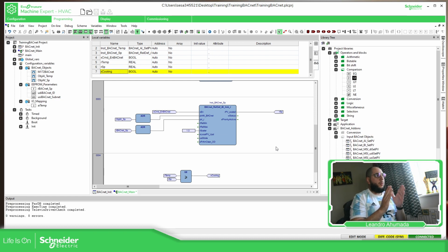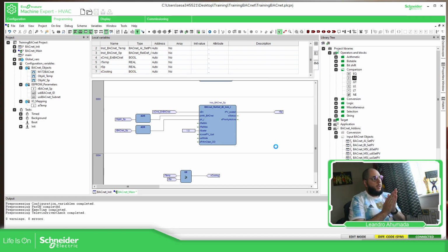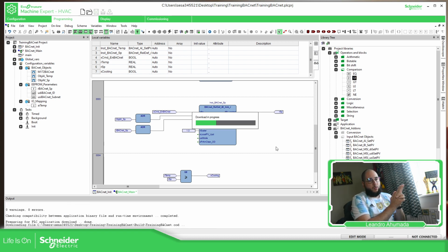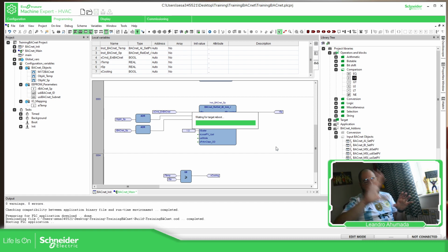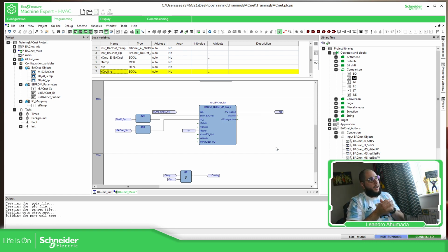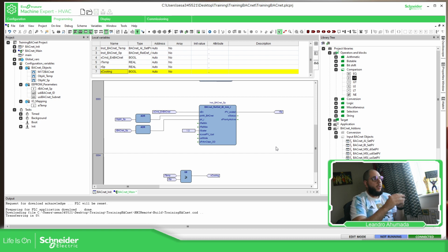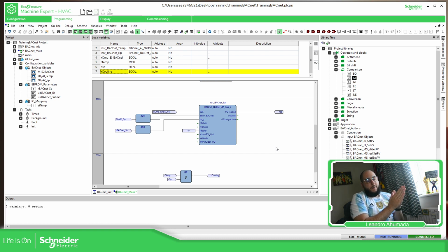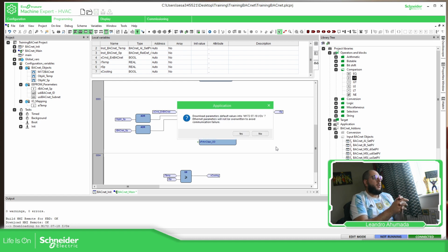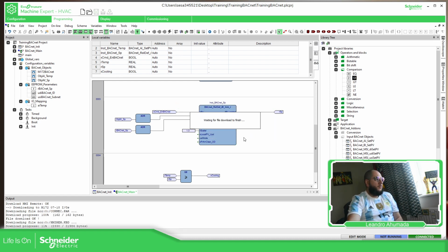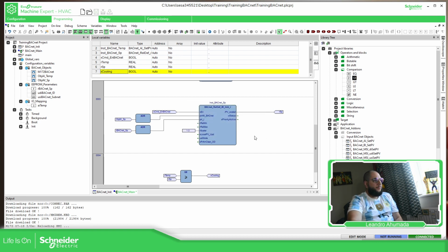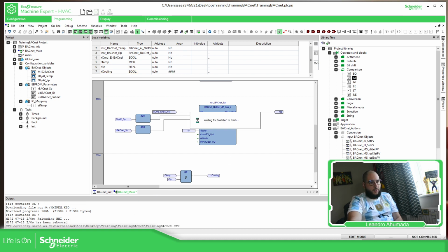So it's important that we identify when to use the analog input and the analog value object here. Analog input is when you want to send information from the PLC to the BMS, and analog values are when you want to receive from the BMS into the PLC, and then make everything. And for each kind of object, you have different functions to use. That would be the best and easy way to do it.